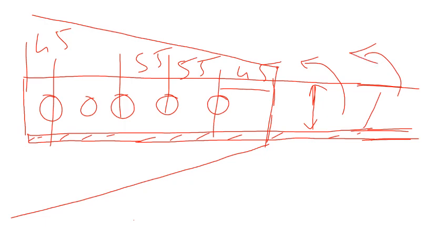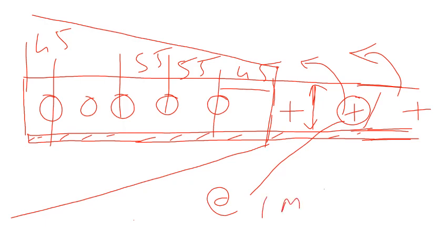So these are called tacking rivets. One will be here, one will be here, one will be here, so that both the angles will act as a single unit. So these tacking rivets should be provided at a distance of 1 meter center to center, right?